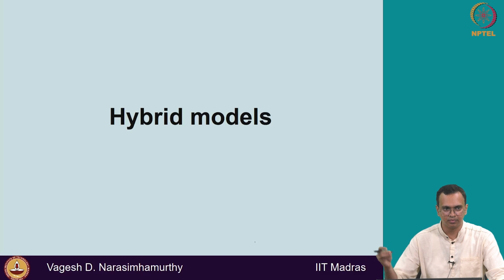Then the whole point of using LES is actually being defeated, becoming very expensive and not being affordable also in many cases. So then the idea came, like, how about mixing RANS and LES? Okay, RANS is affordable and a lot of development has happened for many decades. So it's stable and you can use it, but it does not give you turbulent data. Turbulent fluctuations are not computed. LES computes, but wall resolved LES is expensive.